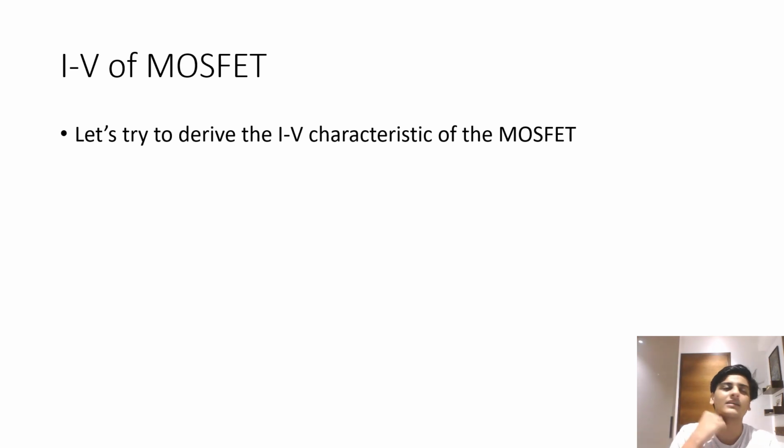And if it can conduct very easily, then if you take a drain and a source, which are just technical names for terminals across which you apply a voltage, that inversion layer can conduct from the drain to the source. So when the gate voltage is high, the MOSFET can be on and conducting, and when the gate voltage is low, the MOSFET can be off and non-conducting because you no longer have that inversion layer. This is the principle on which a MOSFET works.